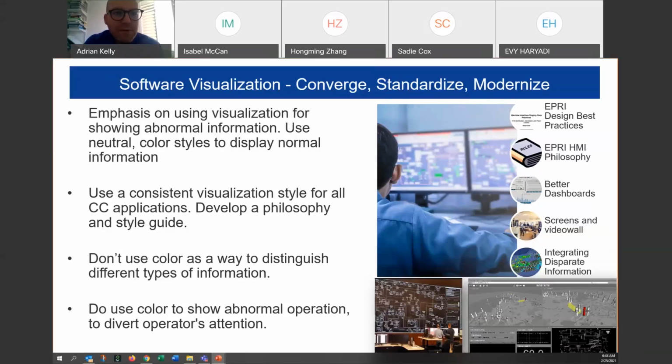So if you have a color, for example, red is priority 1 color. If you see red in your EMS, that's danger. That means get somebody to site to fix something. If you see it in a WAM system, that means that's danger. There's an oscillation happening on your system. I need to dispatch on the system to fix.